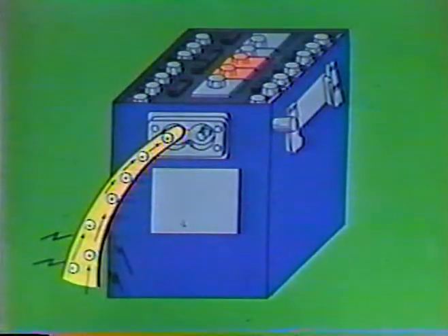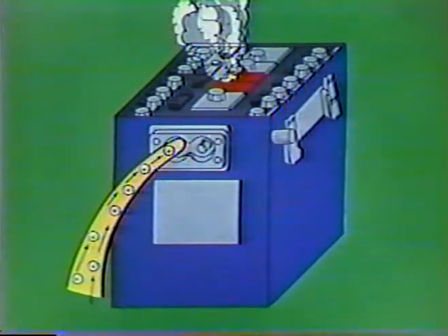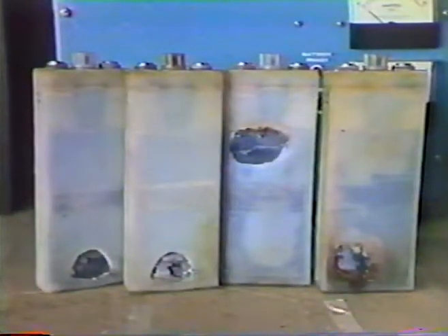When the engine does start and the generator comes online, a high current is immediately put back into the battery, which aggravates this condition further. If some of the cells are unbalanced because of large temperature differences, the high current output of the generator will continue to cause still more heat. This further lowers resistance of the affected cells. This condition is known as thermal runaway and can become critical to the point of destroying the battery.